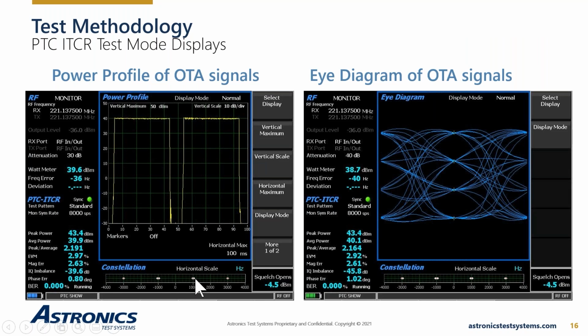So these little white dots would be where the symbols are located, and this is the carrier frequency and the deviation above and below the carrier frequency. And as the signal gets noisier and noisier, they would spread out. You start to get point clouds instead of dots. Yeah, and so you can see that in all 3 of those screens.